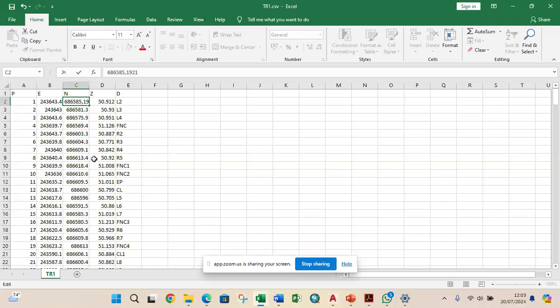Where is the error coming from? So you'll be checking. If there's a comma in one of the data, it will affect you from importing the point into Civil 3D. Once you import, it will give an error that the file format is not found. You can now do a further check, and you see that I've removed the header, my Excel workbook is closed, but why is my point still not importing? You have to try and check and do a finding, and you see that there's 1 point or 2 or 3 that has a comma sign instead of a dot. That disrupts the entire process of importing your data.